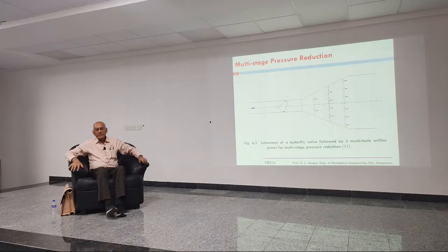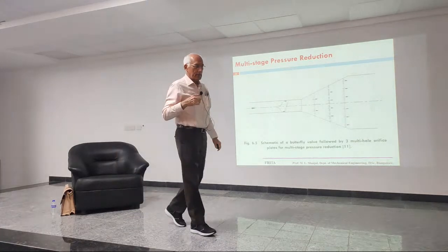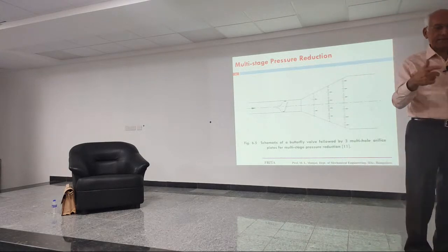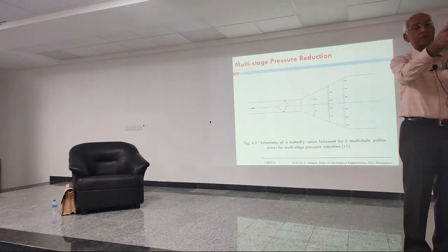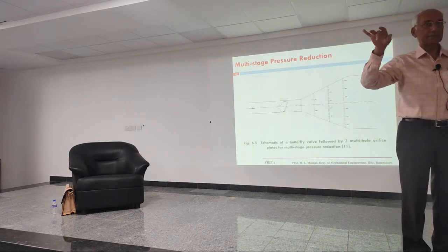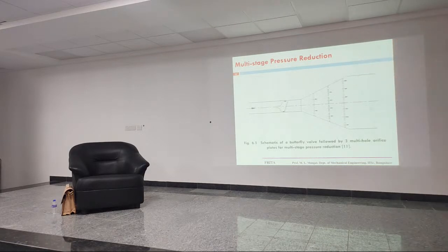This is very important. Please understand that if a boiler has to be started and brought to give you 18 kilograms per second at 200 bars pressure, it takes 48 hours to stabilize. Now let us say something happens and you don't need that steam. You can't just say close the boiler, because 48 hours are gone. So you have to just vent it out. That's why the word vent.